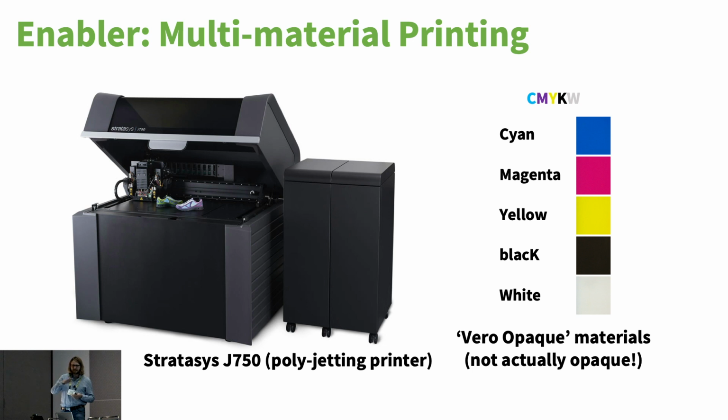So you just inkjet your 3D printout layer by layer, and shine UV light on each of these layers and build the 3D print like that. And this is really the one and only technology today that can achieve full color textured 3D prints, where each of these droplets is just 20 microns. So really, you're getting some level of detail that's quite amazing.